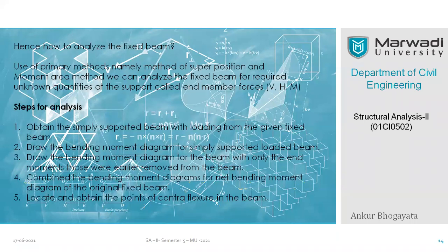Okay, now what are the steps for the analysis? Obtain the simply supported beam with loading from the given fixed beam. That is a very important and first step. Obtain the simply supported beam with loading from the given fixed beam. So that means you remove the fixity, right? That is the first step. That is your ideal step.